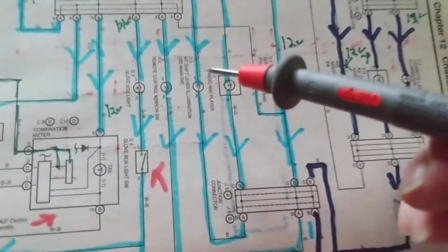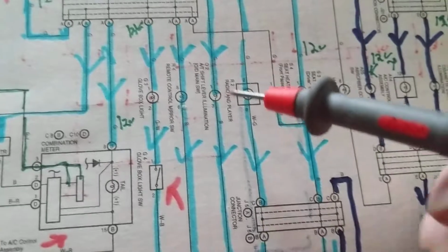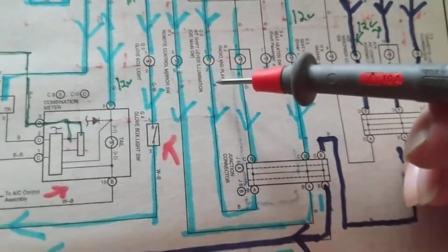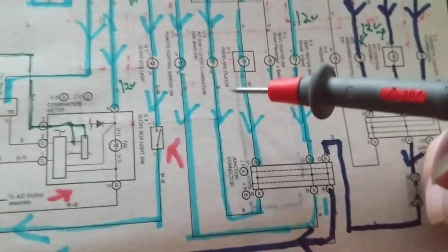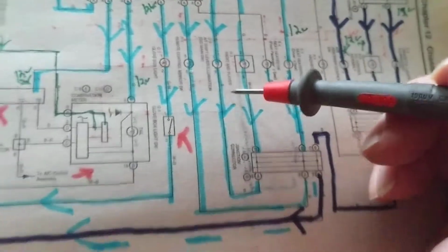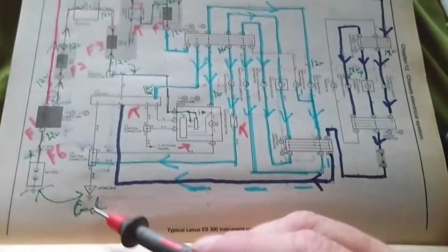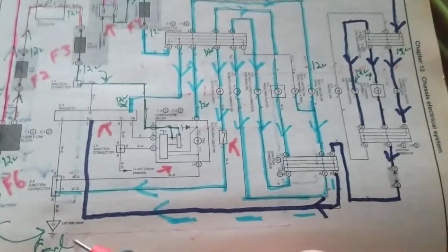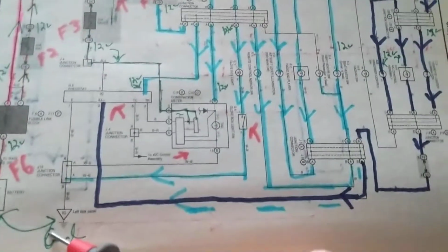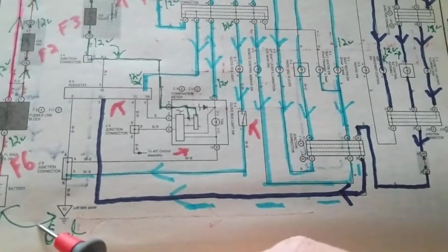In other words, if I want to measure this bulb, this represents a bulb, a light, I put this across, and I put the other side, the negative, across the other side. Now, we usually leave one probe at ground. This is ground. Take a look at the schematic. This is ground. So, we're measuring with reference to ground. We always leave the negative at one point at ground. It's more convenient that way.